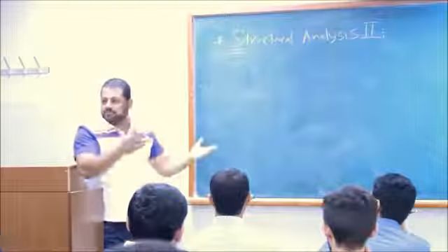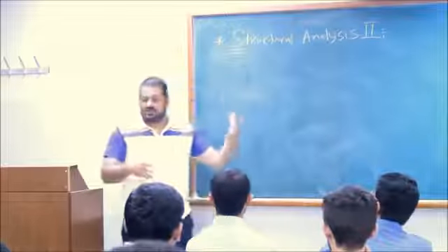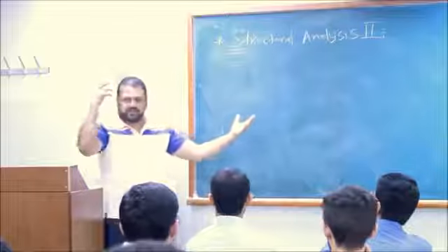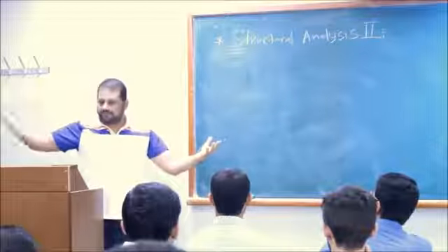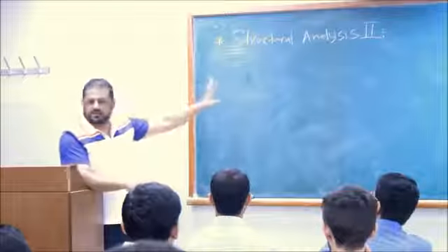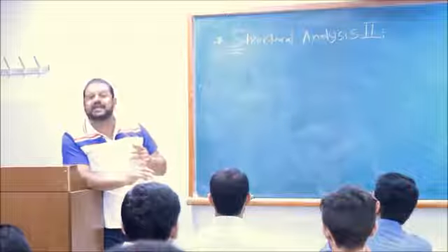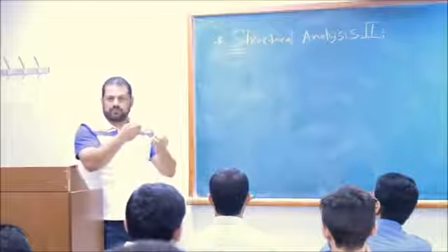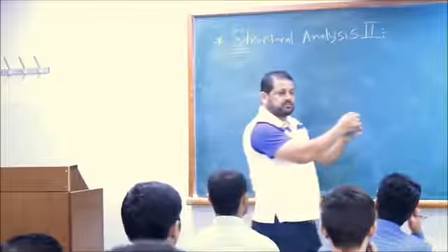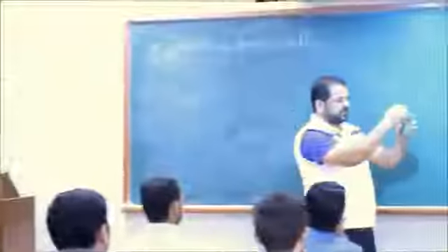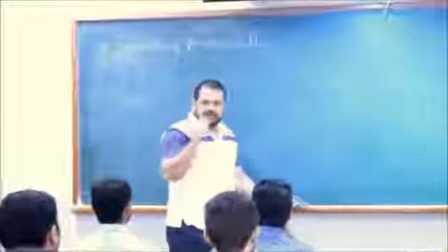Then we write compatibility. Like at the support, we know there is no vertical deflection. There is the deflection from the first case, plus the deflection from the second case when we introduce one of the unknowns, plus the deflection from the third case should give you zero deflection at this location. This is called compatibility. You can say deflection compatibility or strain compatibility. Compatibility, guys, if there are 2 points connected, and you calculate the deflection for this location here, it should be the same. Let me give you an example.